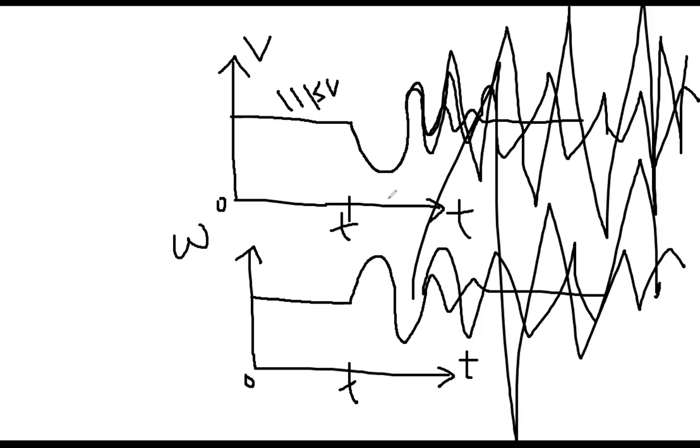So therefore, in this class we are looking at power system stability, meaning that there can be a fault, there can be some oscillation, but after some oscillation, it comes back to the desired position. In case of the voltage, the speed or the frequency, it may go high, then come, and after some oscillation it comes back. Depending on the fault, it might automatically come back to the original position. Sometimes it does not come back. It depends on the severity of the fault. If there is a high peak, it might not come back. That's why you need to put some control means, stability control means.